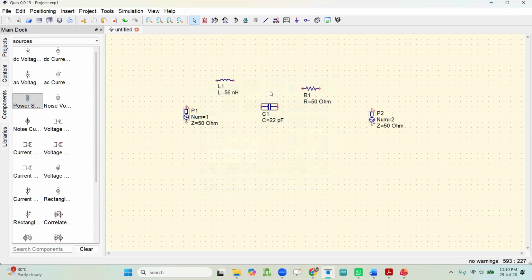In order to turn the components, you have an option, turn component to vertical position. Similarly, let us change the resistor component to vertical position for the perfect matching of the circuit to the L shape.